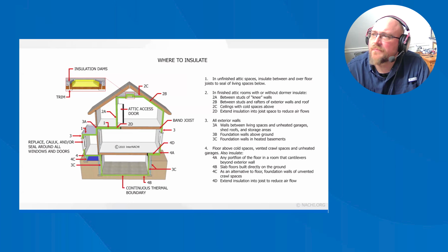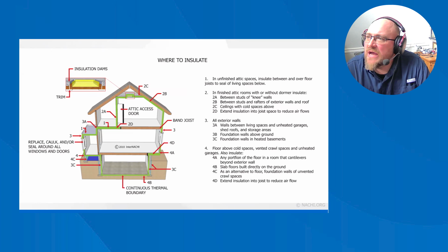Where are we at? Let's see, insulation that is compressed will not provide its full rated R value. The overall R value of a wall or ceiling will be somewhat different from the R value of the insulation itself because some heat flows around the insulation through studs and joists. If denser, heavier insulation is installed on top of lighter insulation in the attic floor area, the overall value may be different. If R19 batt insulation that is sized for 6¼ inches is stuffed inside a 5½ inch wall cavity, the effectiveness is decreased. If the insulation is installed in a wall with electric wires or plumbing pipes, the fiberglass batt insulation may be compressed.